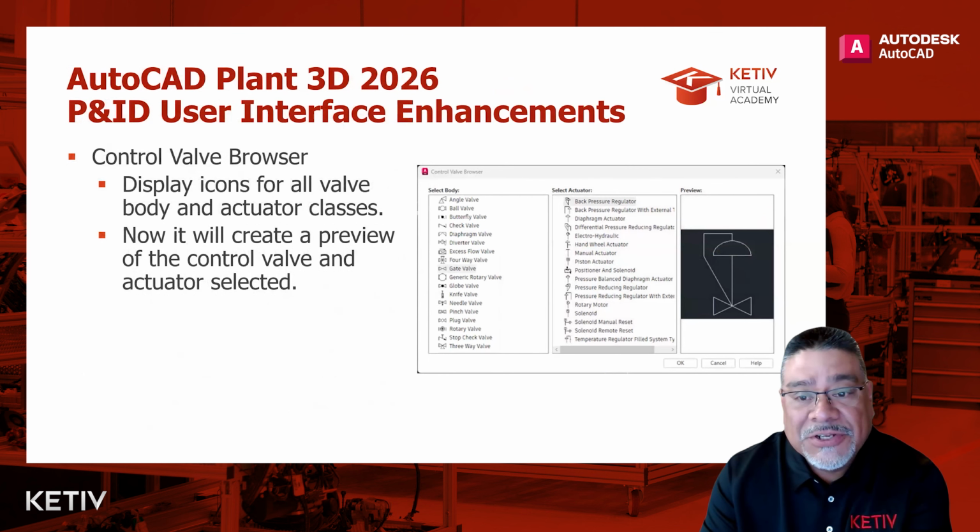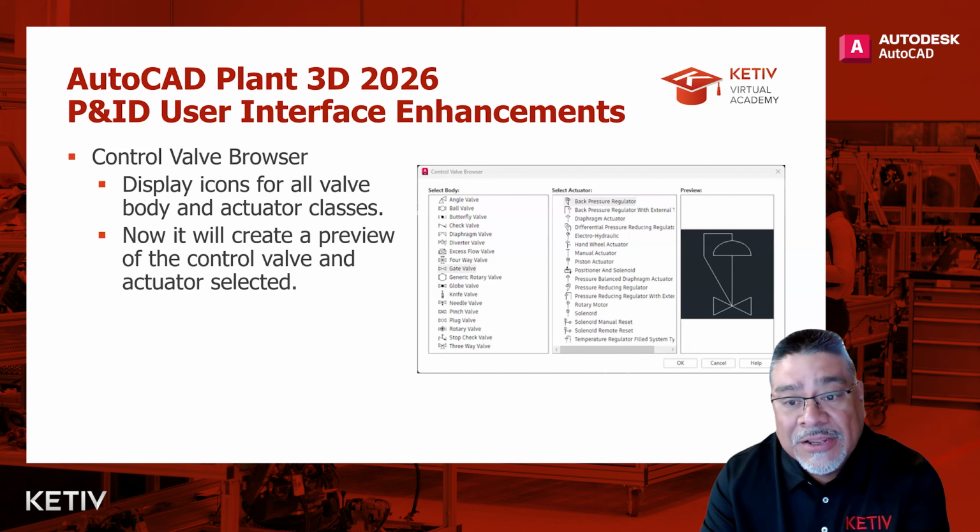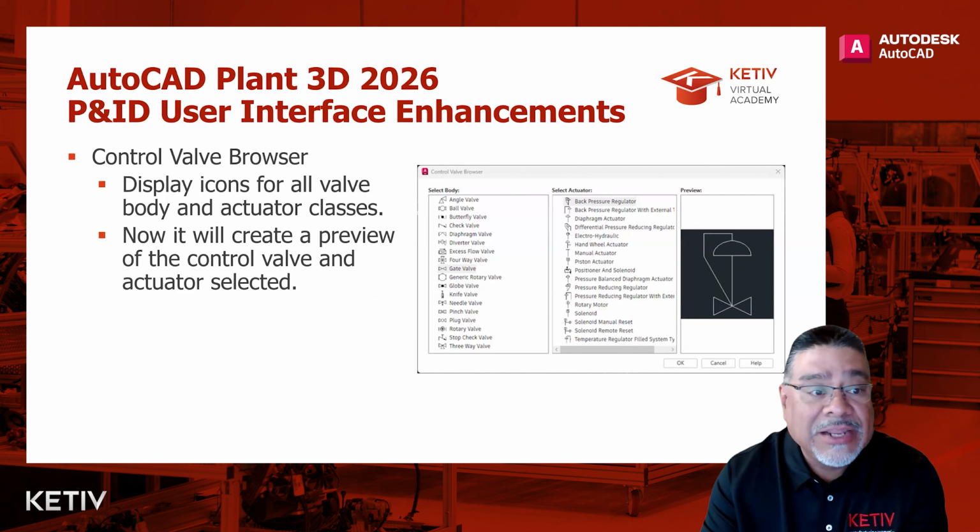One of the first things you'll notice is that traditionally, when you would go into the P&ID program with the user interface, for instance on the control valve browser, whenever you're selecting a control valve to insert into a drawing, you would see just the initial part of the valve body. But now with the new improved UI, the icons for all the valve bodies and actuator classes are shown in here. So you also get the visual representation of what it looks like, and then also the description for both the body and the actuator.